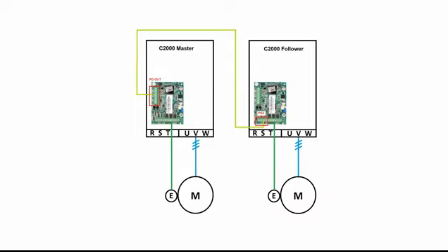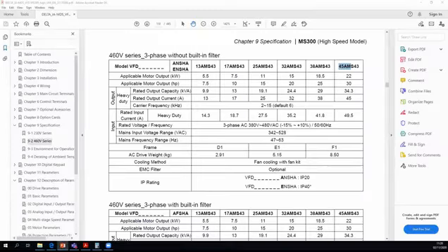Okay, so moving on to how to connect to the drive with Ethernet IP and control it in point-to-point. So firstly, I will open COM Manager. So this is one software which I think most of you are already familiar with.